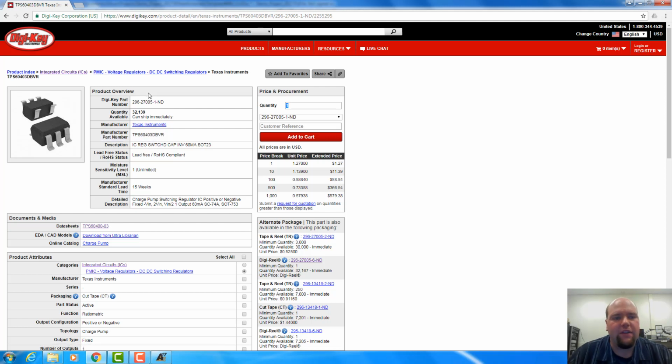The cool thing about this is it allows you to do a relatively small design, and with the exception of the inverting case, these charge pumps are fairly efficient. Using charge pumps to do voltage regulation other than just a clean one-to-one inversion, you start to get really inefficient. So I think charge pumps are about maximum 50% efficiency for doing larger voltage changes.